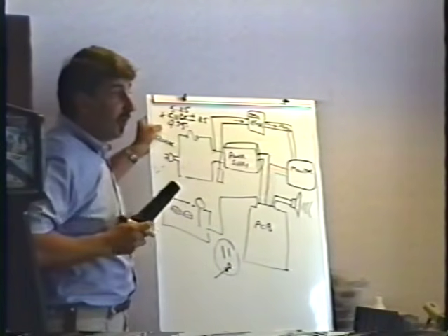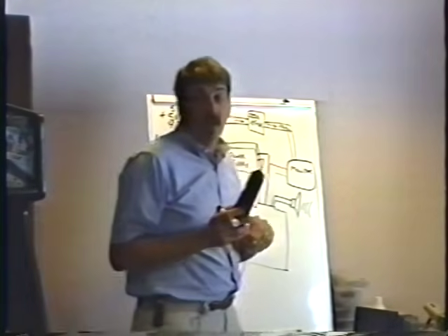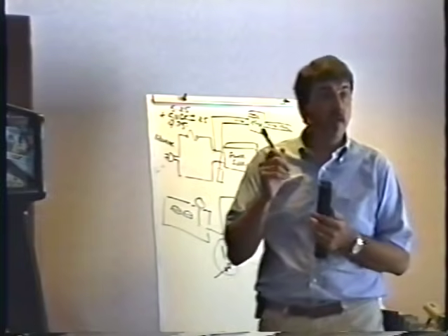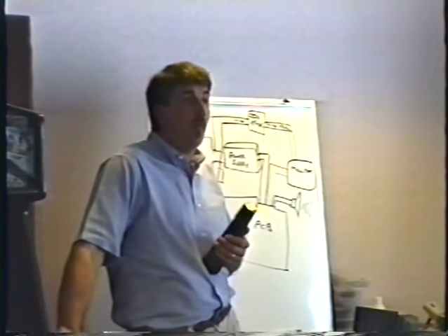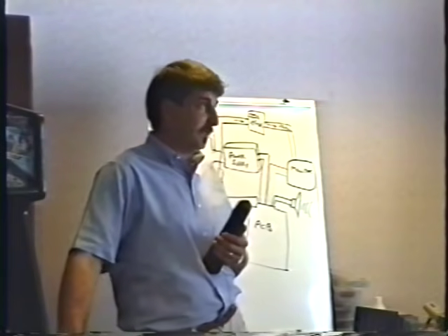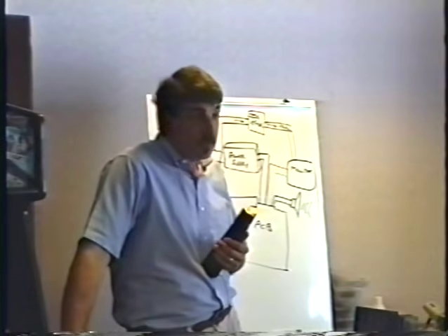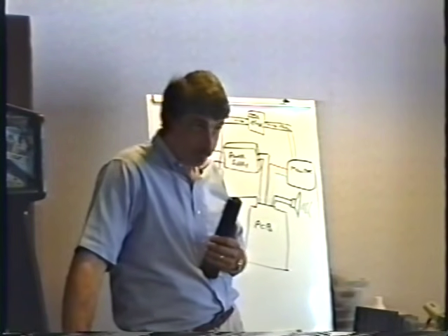Quite frankly, I find that almost nothing works properly at 4.75. Especially like Sky Shark here, it'll crap out at 5 volts even. We set, at Area Amusements, we set all of our games to 5.1 volts. We set the power supplies to 5.1. Some people say 5.17. Well, whatever. 5.1, 5.15, something like that. We just have found that we have far fewer problems that way.